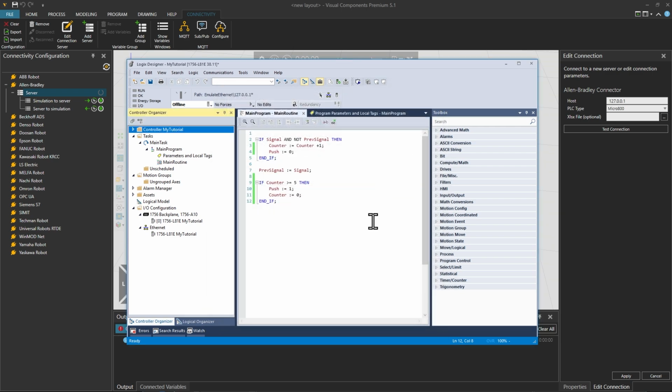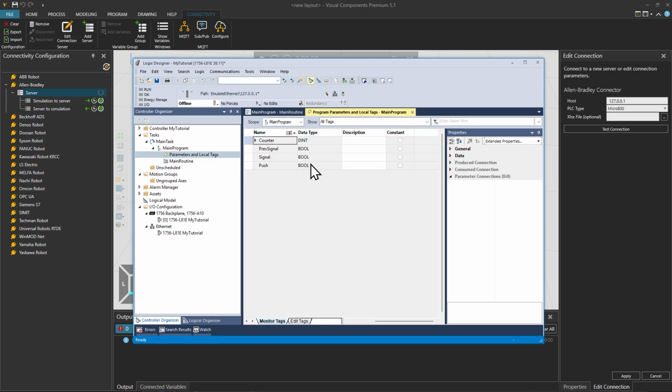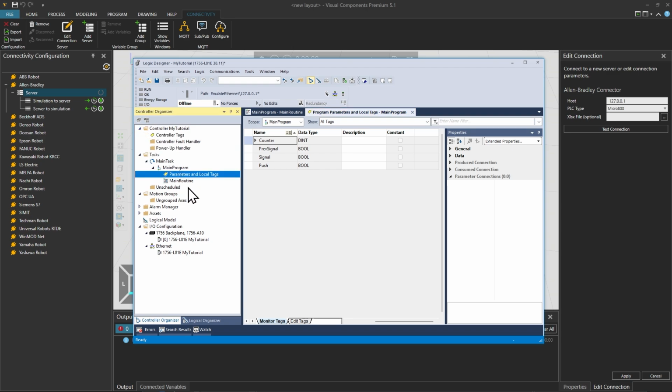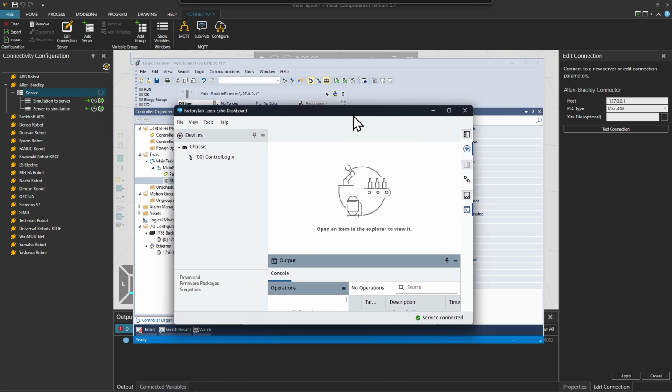We would also need to go online within the system. And in order to go online, we either have to use an emulated PLC or a real PLC. So this Studio 5000 is for configuring the PLC, for example, the ladder diagram or the structured text, and initializing variables in tags. In this case, let's use an emulator, and in order to use an emulator, we need this FactoryTalk Logix Echo.